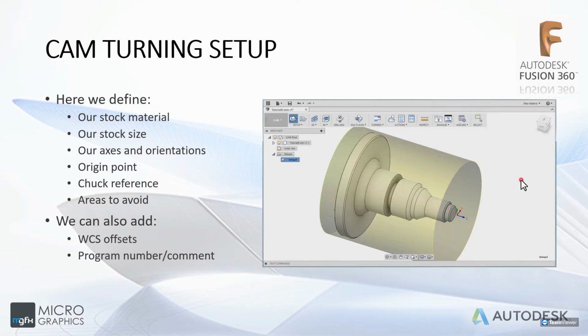Of course, the CNC machine doesn't know anything about the starting stock. So you've got to tell it which way is the Z direction, which way is the X, which way is the Y. You've got to tell it where on the model is 0, 0, 0, meaning your origin point. Again, you'll have all these options to flip them, change them around.